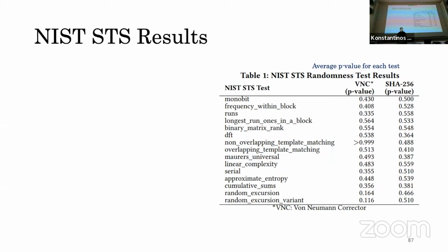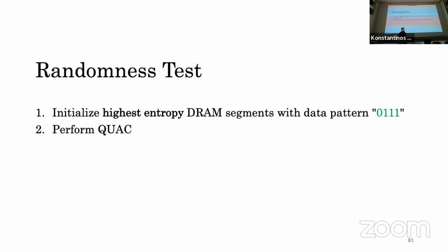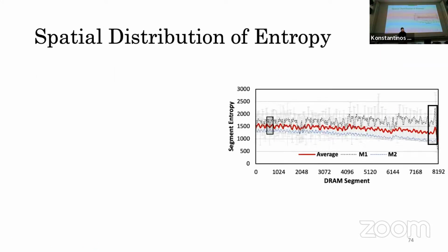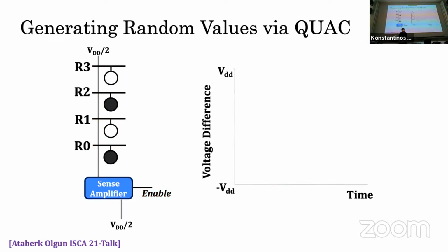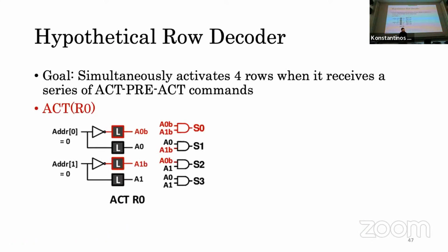do with the DRAM circuitry and how, when you issue a command, which rows are activated, with the row decoder, that's the word. It has a lot to do with the row decoder. As we have seen with the hypothetical row decoder, in order to activate 4 rows at the same time, you need to have this hierarchical DRAM structure. So this is definitely quite important.